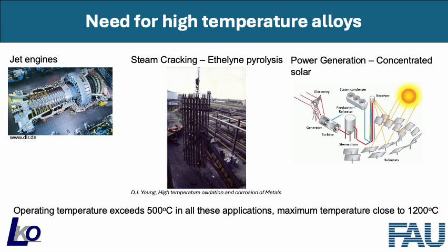And there is an important industrial process of steam cracking, which is used to produce hydrocarbons, for example ethylene pyrolysis. These are held in these big tubes that are there in the picture in the middle. These can operate at temperatures like 700, 800 degrees Celsius. If you see, the pipes look small, but these are very heavy, and the self weight due to gravity acting upon them can itself cause high temperature deformation in the form of creep.